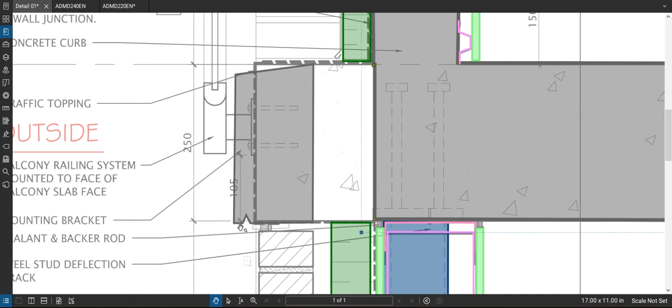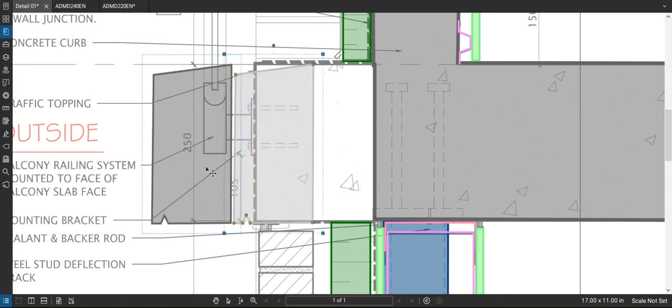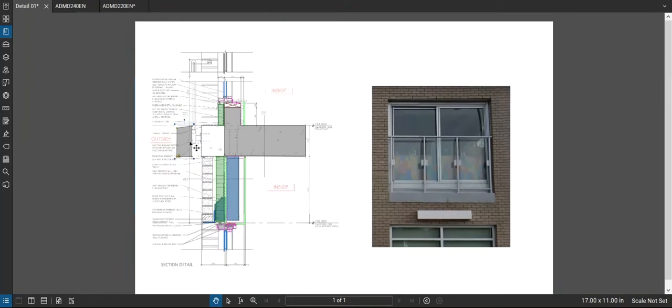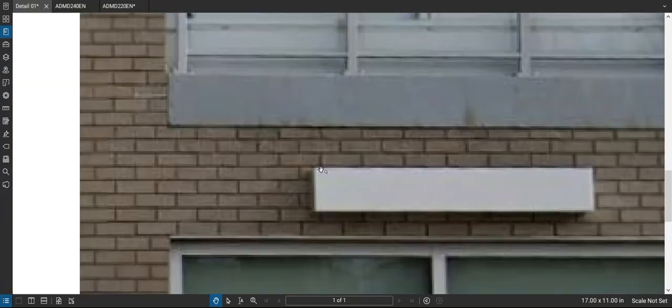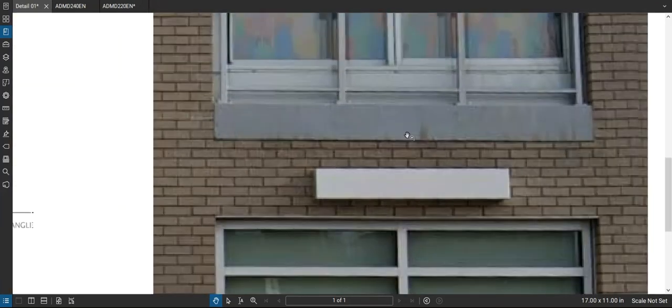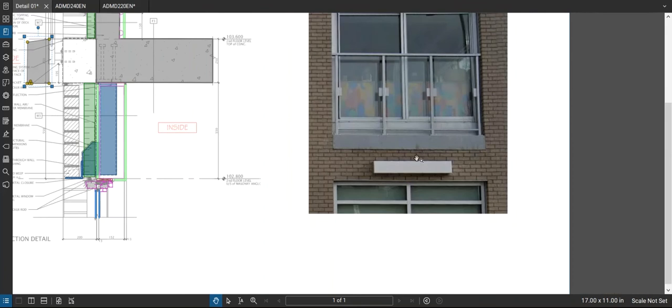So two things are going to happen the way it is right now. There's going to be staining down the brick. Let's just see. My picture's not really clear enough, but I can start to see some staining on the brick there. And the second thing that could potentially start to happen here is efflorescence in that brick. Okay, too much moisture in the brick.